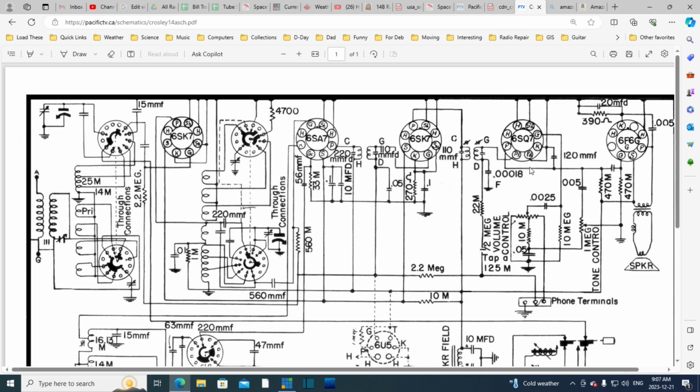So that's my theory. Now, does this mean that this tube is bad? Like, does it have a worn out cathode? And with a worn out cathode, this effect gets stronger and stronger? What about all those radios that I've gone through where I turn the volume down to 0 and can still hear it coming out of the speaker? I've had a number of radios here that you cannot zero out the volume, and I've always attributed it to the volume control. I've never thought of it, that what we could be hearing when the volume is reduced to 0 is a sneaky signal getting right through the tube over to the output tube.